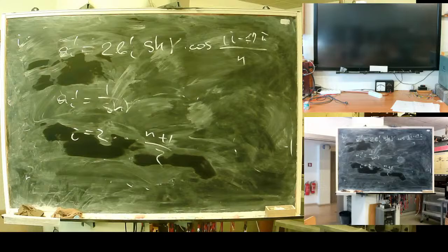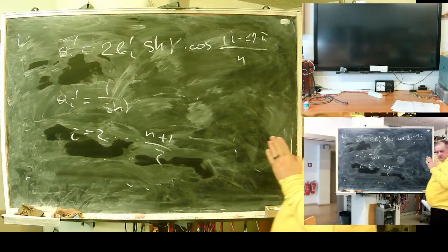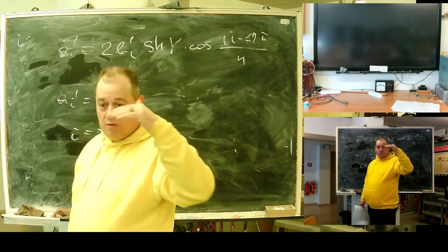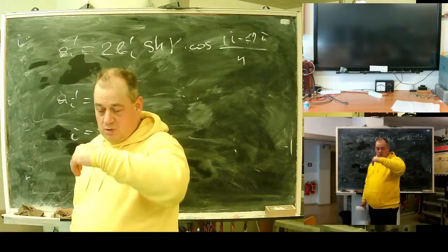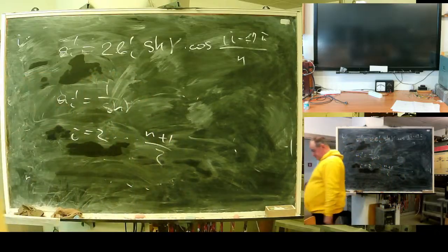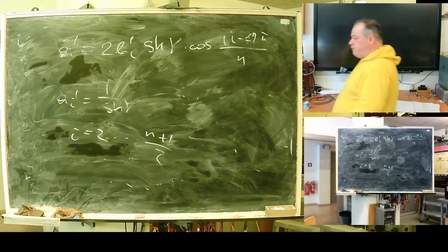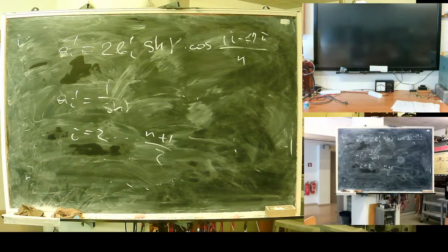What's good about this? A Chebyshev filter ensures better cutoff. It has, how to say, a stiffer slope from pass to reject. But a Chebyshev filter may perform worse on transients.